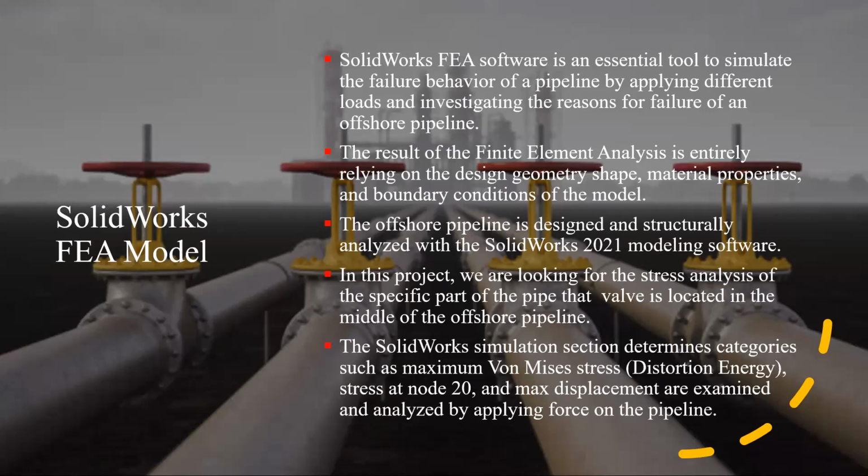FEA software is an essential tool to simulate the failure behavior of a pipeline by applying different loads and investigating the reason for failure of an offshore pipeline. The result of the finite element analysis relies entirely on the design, geometry shape, material properties, and boundary conditions of the model. The offshore pipeline is designed and structurally analyzed with the SolidWorks 2021 modeling software.